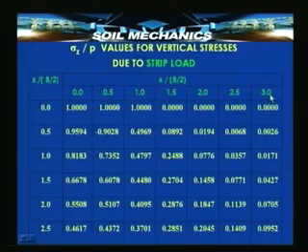The range of z in this chart is 0 to 2.5 and the range of x is from 0 to 3, which means that the use of this table is restricted to a non-dimensional depth of 2.5 and a non-dimensional x coordinate dimension of 3. That means the horizontal width is 3 in non-dimensional terms and the depth in non-dimensional terms of the point at which we want the stress is 2.5.